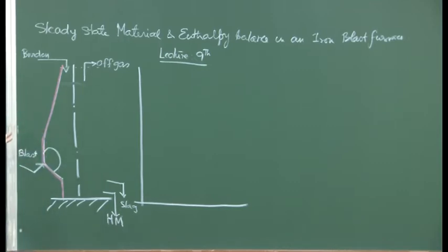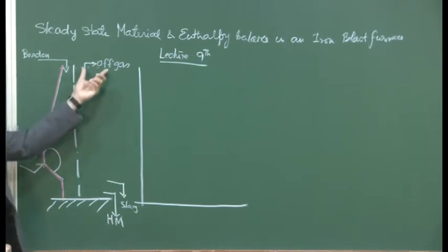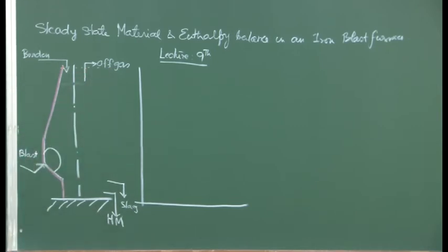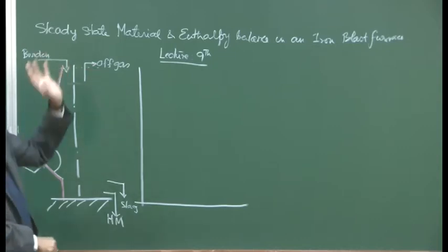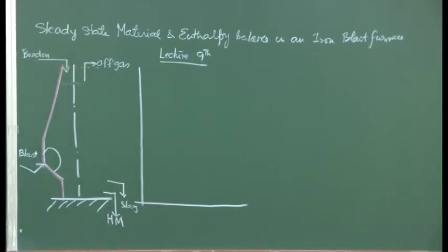furnace. Our objective would be that, in order to produce a given amount of material from a known iron bearing material, how much blast we have to introduce, what should be the volume and composition of the off gas that is going to be generated, and what should be the amount of coke that needs to be charged into the furnace. So key operating parameters will be calculated on the basis of a steady state material and enthalpy balance. We will not discuss the advanced models here; it is sufficient for us to know that there are various stages of models which are available.